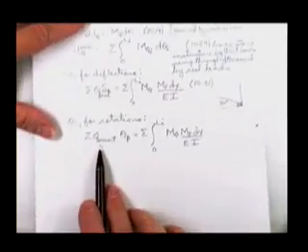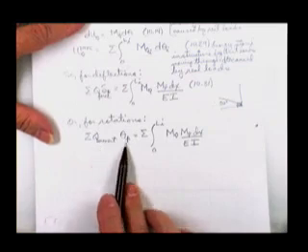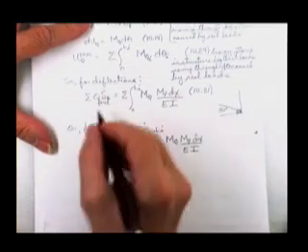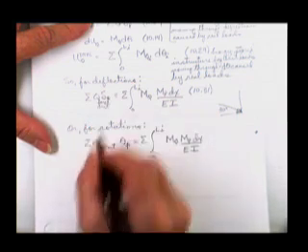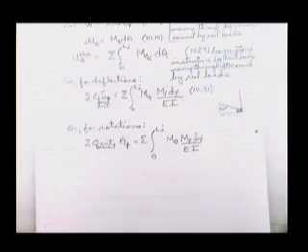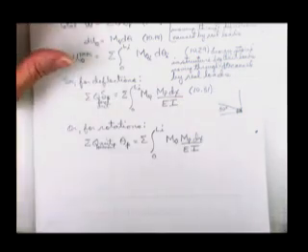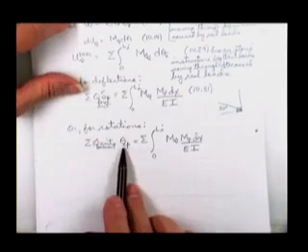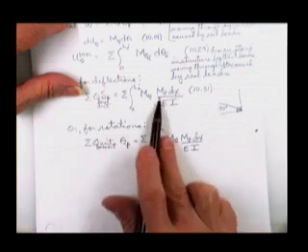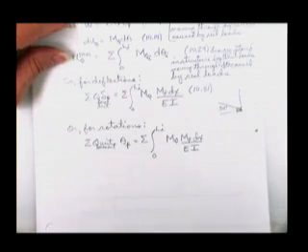The energy stored or the work done on here, if you instead put a moment, then I can multiply the magnitude of the unit moment times the rotation that that unit moment rotated through in the real world due to the real loads, theta p, and set it equal to the same term. The only difference now is m sub q would be due to a moment applied to the structure as opposed to a real linear load applied to the structure.